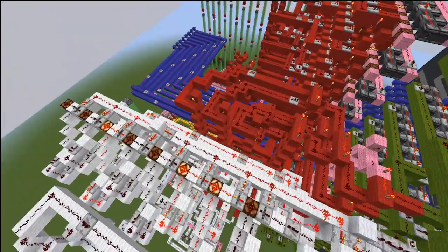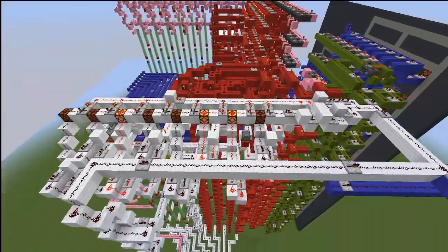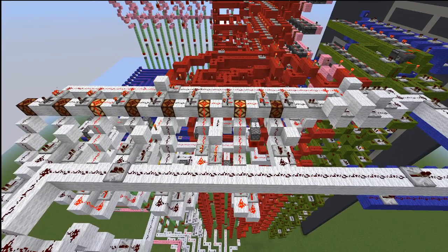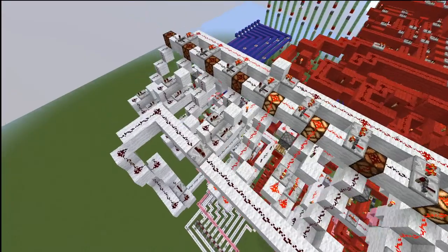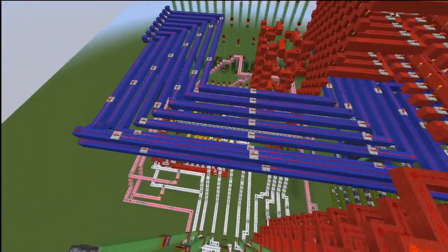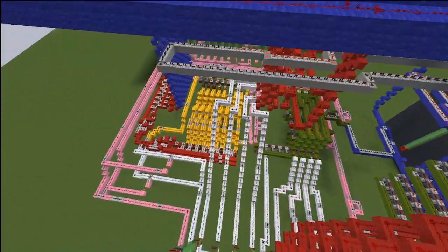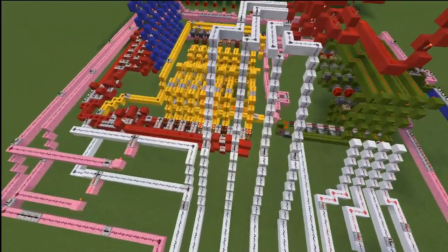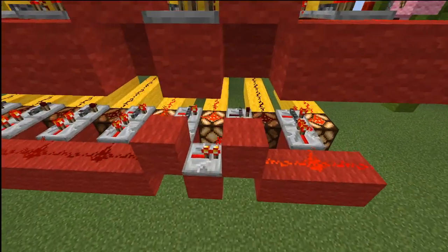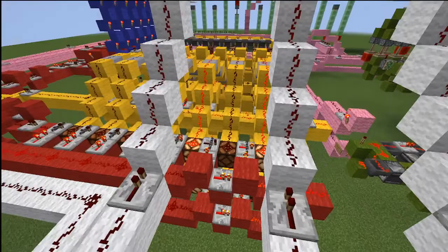So the byte 6, which is on prom line 6, is going to update to this memory address register. We'll see it come in soon. And here's the data. And now it's got that. On the next clock pulse, it's going to update that to the B register, which is down here, right below the A register. It is a bit hard to see the B register, and I apologize for that. But yeah, if you come down here, you'll see the data come in, and here it is.